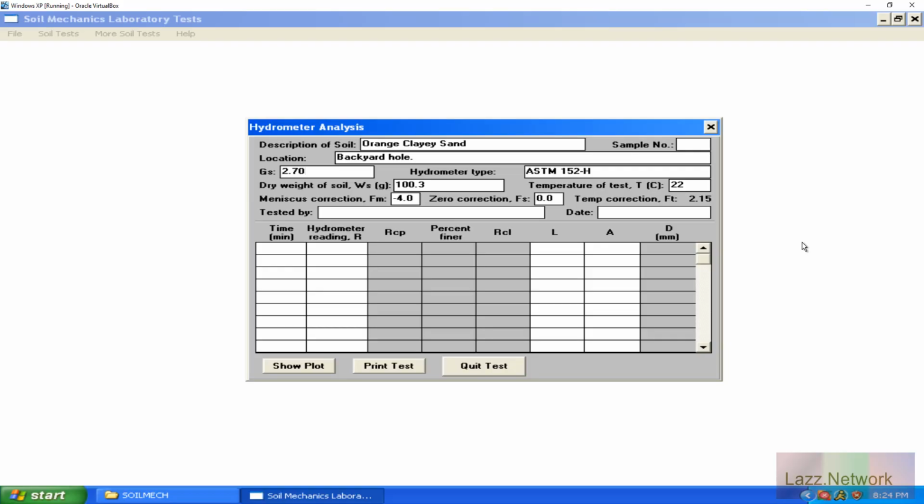You don't want to do that because it could completely change the fact of how much silts to clays that you have. And sometimes with this test, there are certain specifications that require, hey, this needs to only have this much silt and this much clay with this much passing the 200 sieve, like baseball clay. That's like the biggest thing out there that I've dealt with personally, that it needs to be within that specific sweet range for it to be accepted as baseball clay.